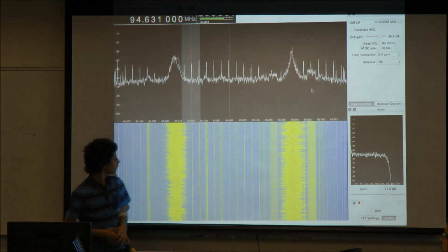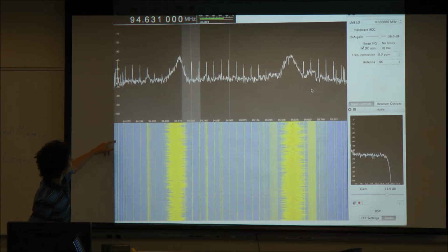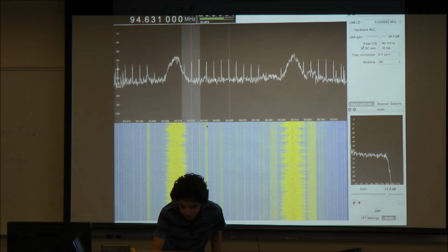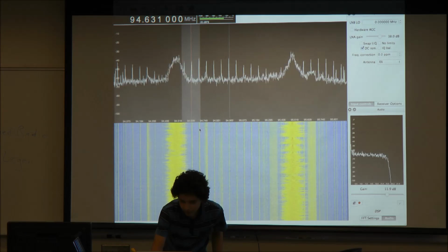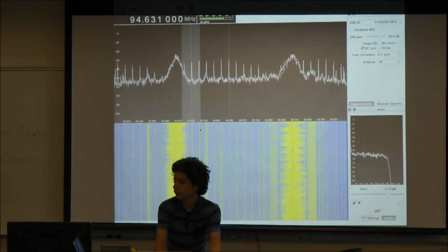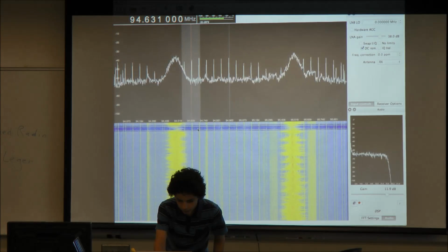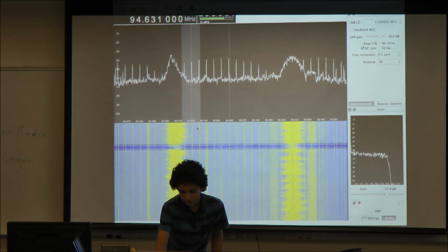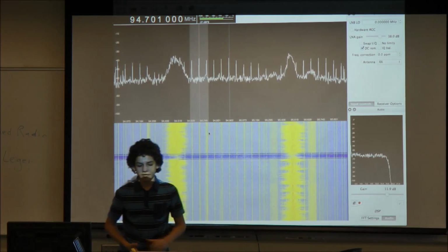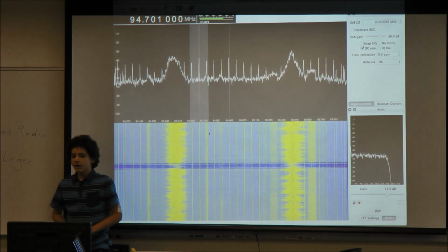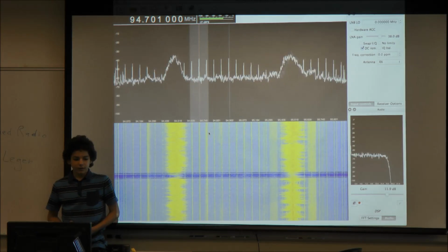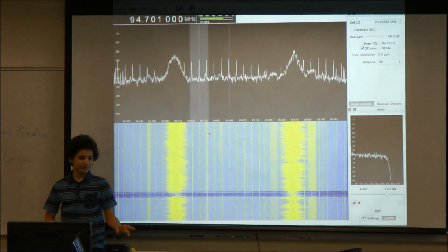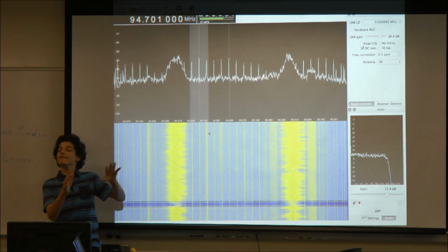I was just wondering what the interval was of those spikes. Of these spikes? Yeah, and it looks like heterodyning. Yeah. Like you actually have your LOs leaking. Well, it wasn't doing it at my house with this same thing. It's probably birdies from something in the room. Yeah, 94.63 megahertz to 94.7, so about 0.7 megahertz. Switching power supply can do that across a wide range. Yeah, well, right now I'm battery powered. Then again, it could be ground looping. RF is weird.